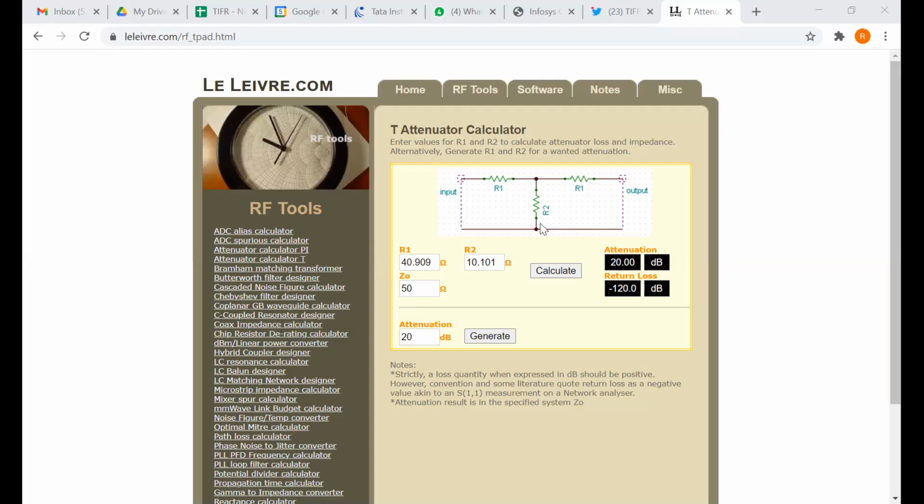And the reason is that because there is such little transmission, the impedance matching to 50 ohms does not rely on the resistor on the other side. It just relies on R1 and R2 mostly. You can also see it from the fact that as the attenuation becomes large, R2 becomes small, and then R1 becomes somewhat large.